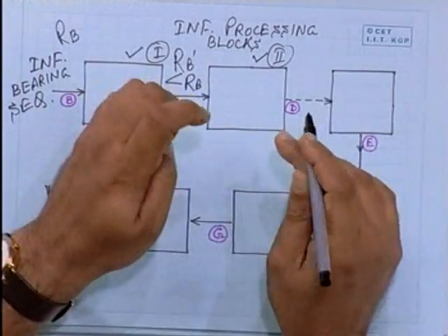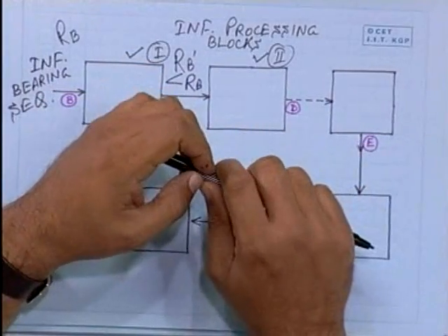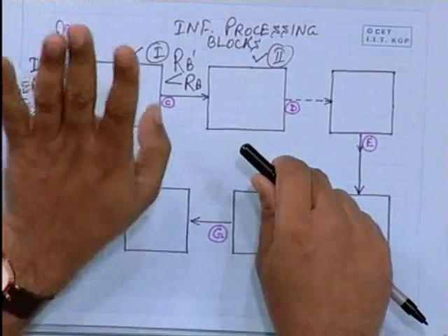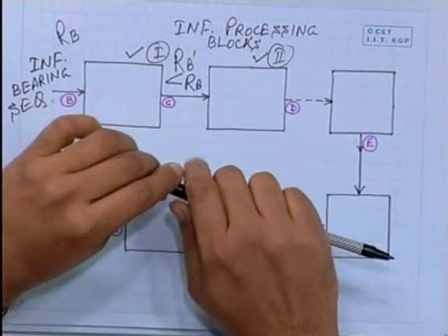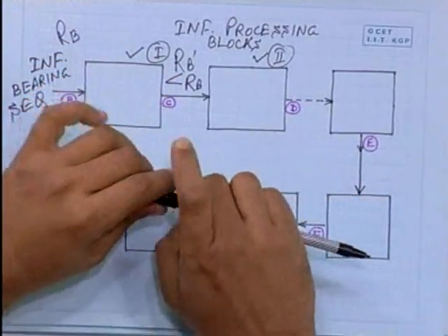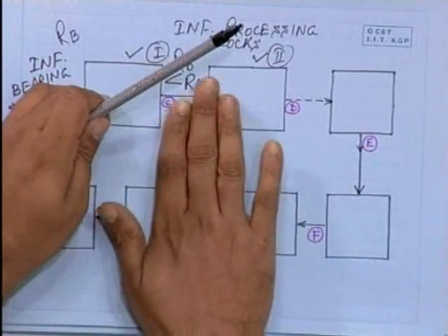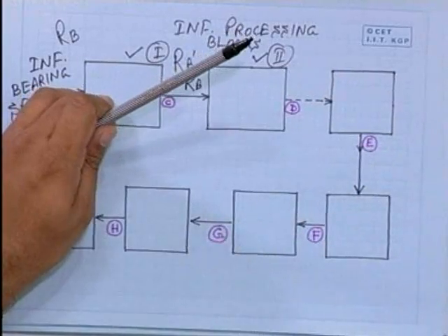The bandwidth of the signal dictates the optimum sampling rate, and then when you decide how many levels are to be there after quantization, you effectively get the bit rate after quantization and sampling. So, the bit rate is decided by the number of quantization levels and the input signal bandwidth through the sampling rate. So, they are related. What I am now talking about is whatever has been done beforehand is fine. Now, starting with this input sequence at a particular bit rate, if I can do some further processing by which I can reduce this bit rate further, that is a net saving perhaps, that is going to be of advantage all through the design of the subsequent modules and even for transmission.